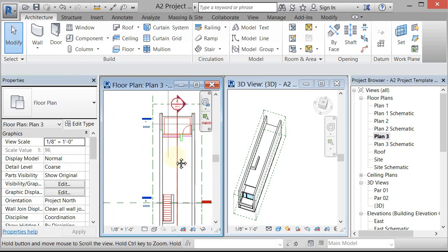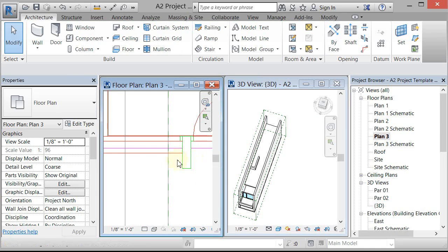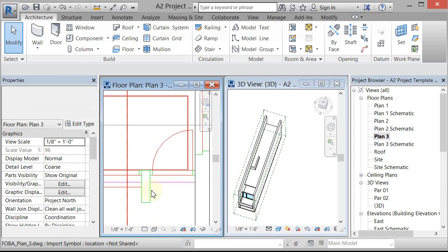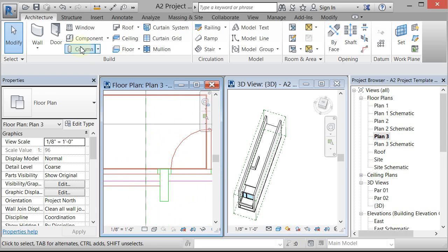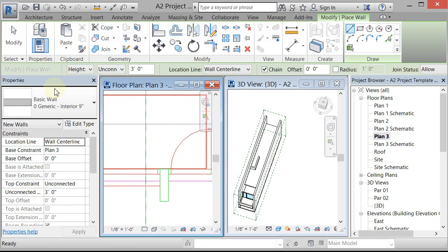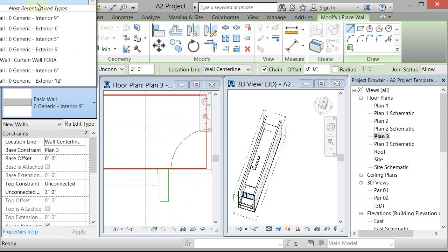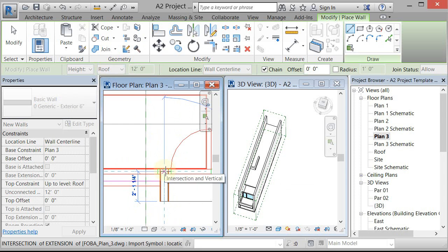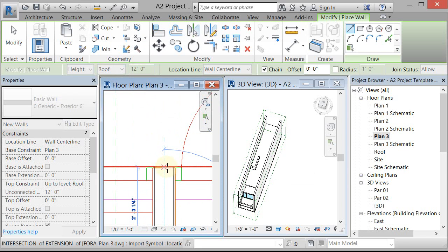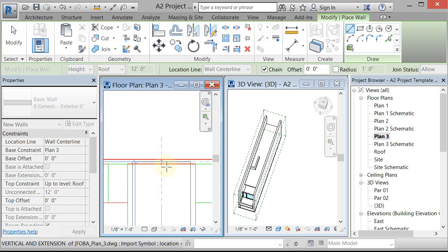And then I'll come in, and it looks like we have 2 curtain walls here, one with a door and then a big wall in the middle. So I'll go to wall. I think this is a 6-inch wall if I remember. So an exterior 6-inch. And we can just go right down the middle. Right here. It looks like it's a little bigger, of course. It'll be a little different.